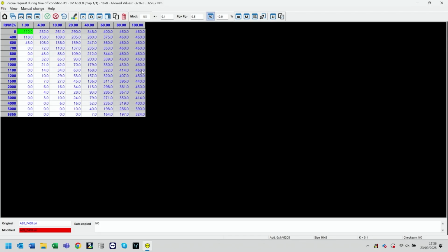So we're going to open our torque request map. Now, our torque request map actually sits above that 400 Newton meters, 390, 400 that we're aiming for, but we're a lot closer to that value now. As we can see, the standard requests were way up and above what the standard vehicle could do. So as a kind of housekeeping